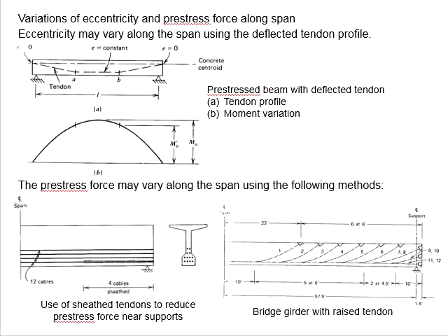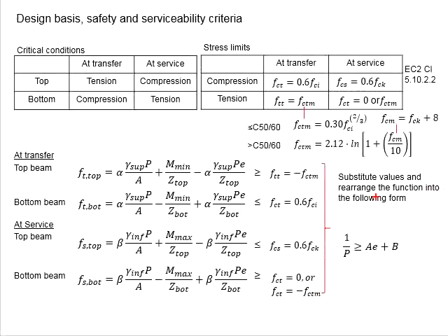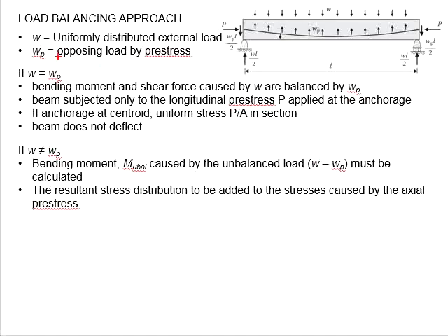the member. We know that the moment generated by the prestressing load will cancel out with the moment caused by the external load, which will lead to the remaining stress that is bounded by its stress limit. As long as the stress within the members is always within the limit, the prestressed member will be stable. This comes to the concept of load balancing.